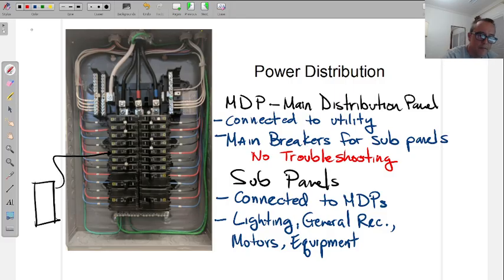Now, do you have to memorize? You don't have to. If you forget that, it's okay, but other side to the neutral is fine, or other side to the ground is fine. Whichever one is least dangerous to have with your meter, keeping in mind you're using 2 hands now.